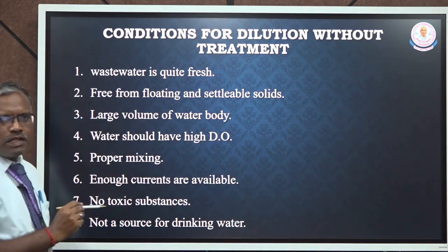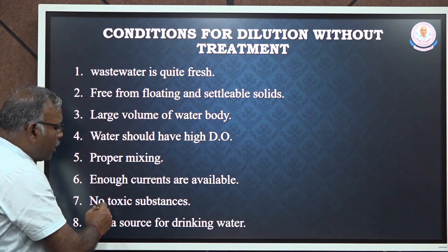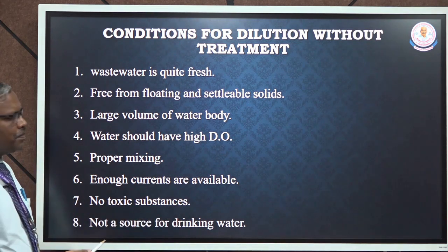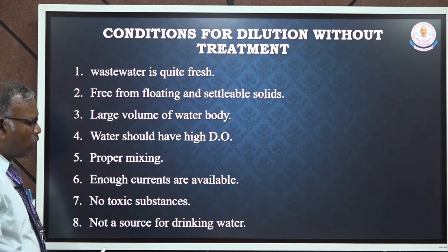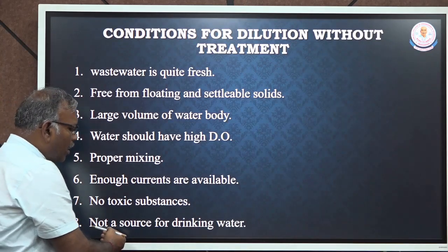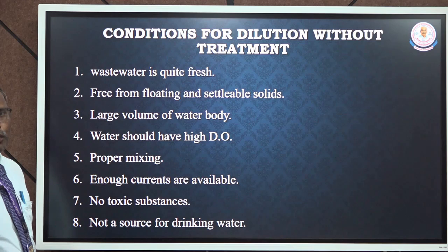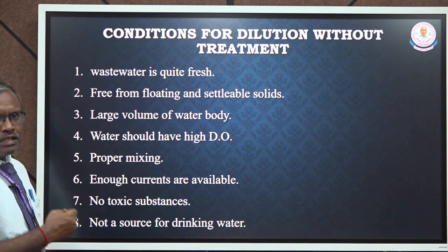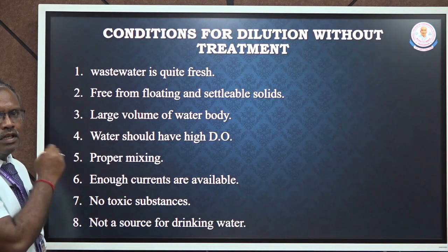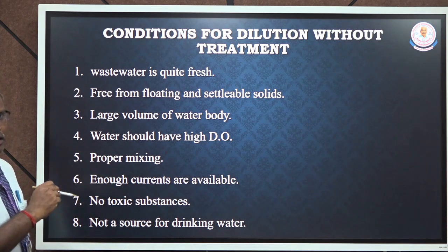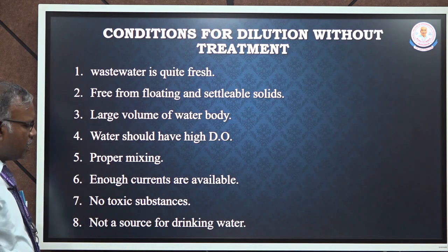The water should contain enough currents, which ensure the proper mixing process. Next, there should not be any toxic substance, because toxic substances may affect the aquatic organisms, and the water should not be a source of drinking water. If it is used for drinking purposes, it needs to be treated before the sewage is disposed into it.